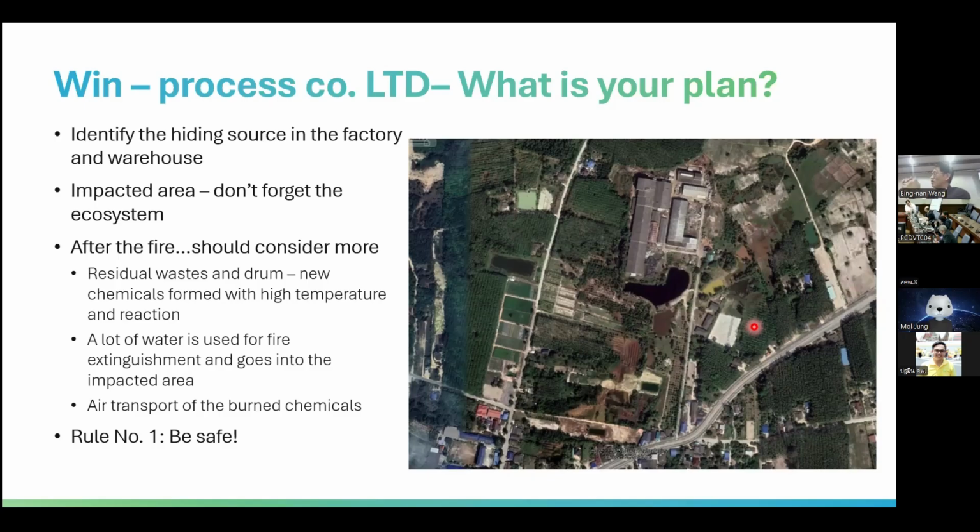You already know the depth of the lagoon, so you can take samples near the lagoon, maybe at 5 or 6 meters. You can then know the potential leaking, potential exchange from the lagoon to the surrounding groundwater.